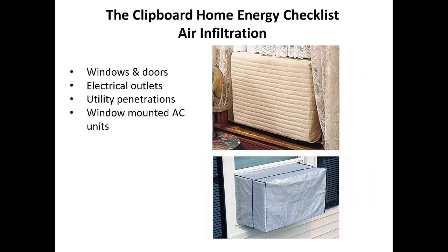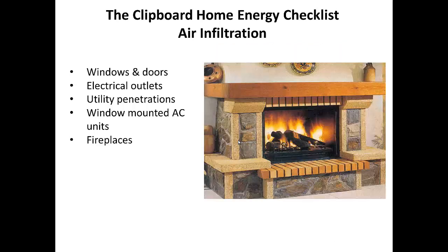Air conditioners. On a cold, windy day, you can feel air coming through that air conditioner. So get on the outside of your house and put a cover over it of some sort. They're available at hardware stores, and you can work on the inside and the outside to help reduce that air infiltration, enemy number one. Around fireplaces, this doesn't have a very good shot. If I had time today, I'd take a picture of my fireplace, but all around the perimeter here, I went around and caulked my fireplace. A lot of times the masonry on a fireplace is on the outside of the home.